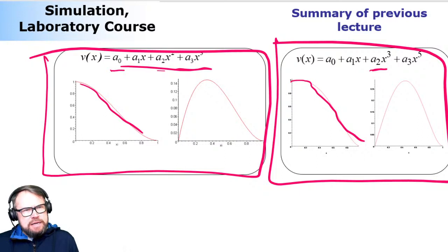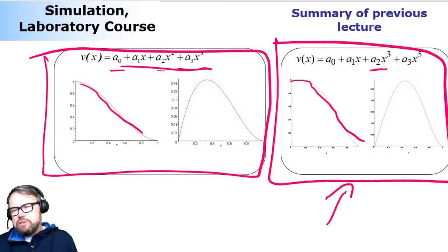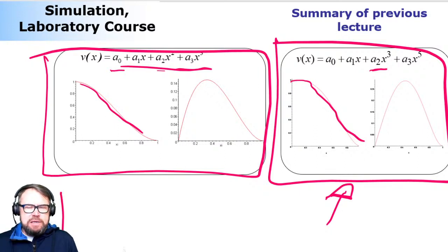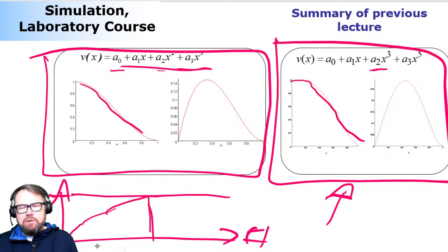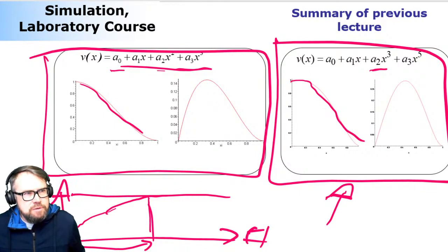And in certain cases, I cannot say all the cases, but in certain cases, you can improve the convergence by selecting, or let's say skipping, some of the polynomials and replacing the low order polynomials by higher order polynomials. And again, convergence means that if this is the number of elements, and this is the correct solution, it means how fast you can reach an acceptable solution. Like how many elements are needed. Shorter the length, I mean, fewer elements you need, better the convergence rate. And of course, you would like to have as good a convergence rate as possible.